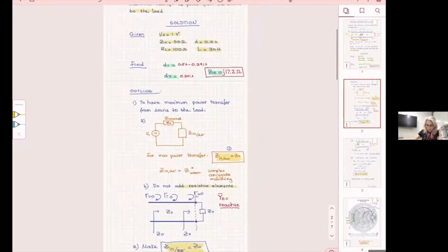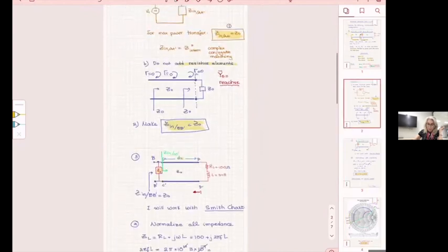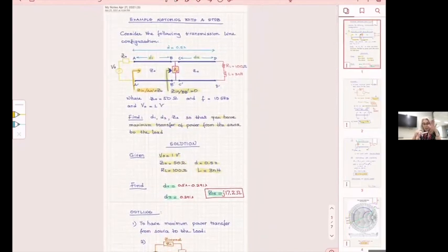What we're gonna do then, power. Since I was able to match the input at BB prime to 50 ohms, practically everywhere on the line, from AA prime to BB prime, I have a perfect match, which means that whatever power goes from V naught into the line, it is all eventually absorbed by the resistor, the real power.